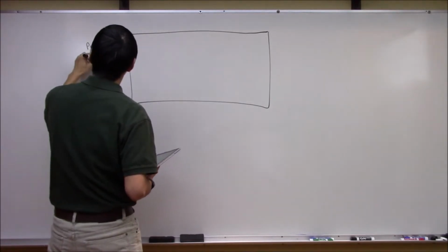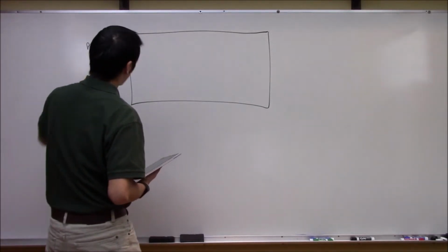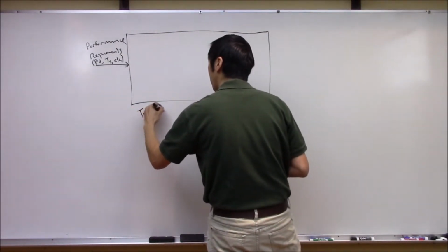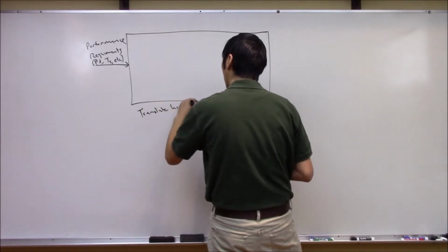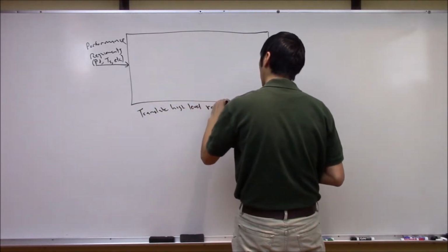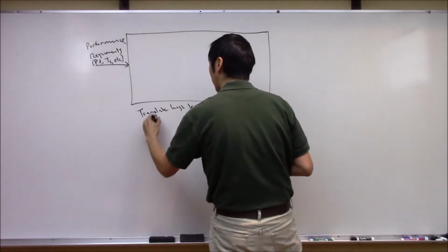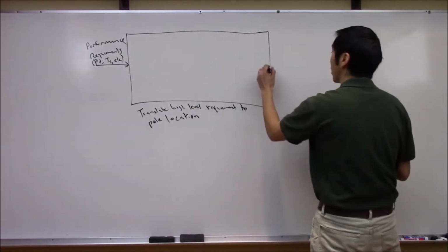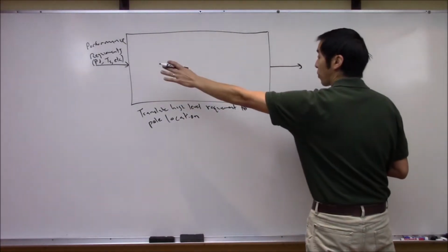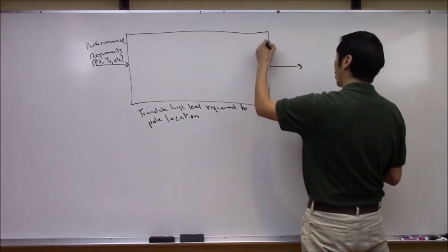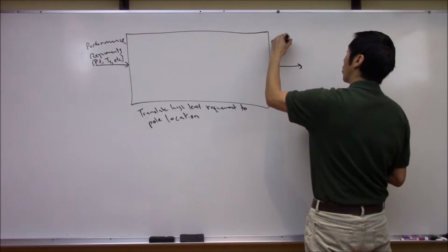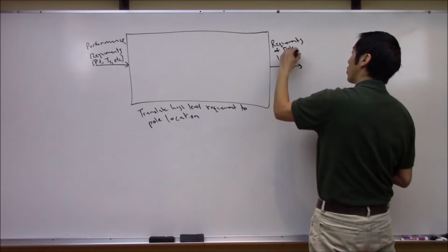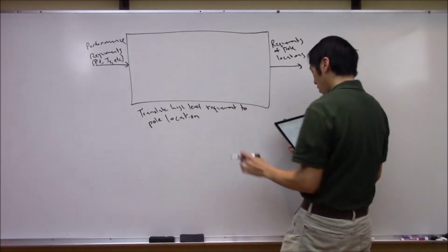These might be things like percent overshoot, settling time, etc., right? And the point of this box here was to translate these high-level requirements to pole locations effectively, right? These would be things like engineering specifications. So out the other end here, we said that those performance requirements were going to place some kind of restriction on the requirements of the pole locations, right? And we said that the way we're going to translate between these two, the first thing we were going to do was time domain analysis.